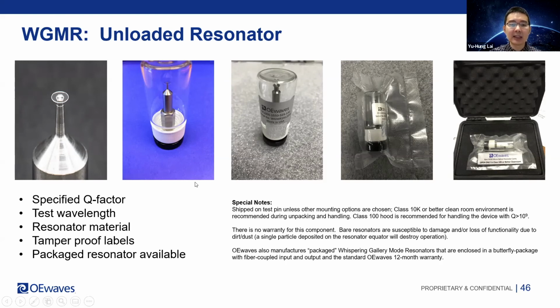Because this kind of device is very sensitive to the environment, we do not provide a warranty for this kind of component. When dealing with this kind of device, a class 10,000 clean room is necessary to open and unpack the package, and a class 100 hood is recommended for handling a device with a quality factor larger than 1 billion.